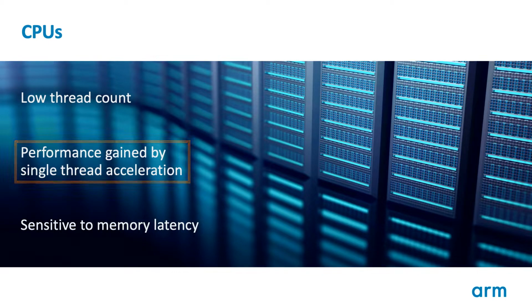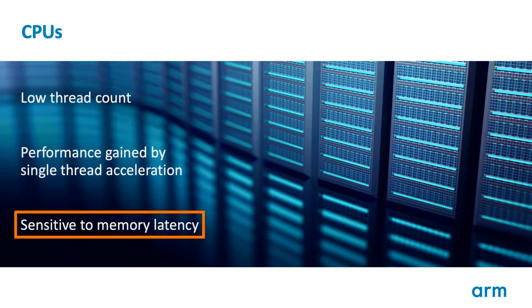In addition, faster CPUs need fast access to data. Any data accesses which need to read from DRAM may have hundreds of CPU cycles of latency to get a result. If this happens too often, the CPU may simply run out of work to do and start to stall, waiting for the data to arrive.